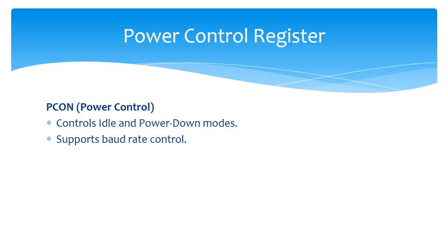You have the next control register, which is called the power control register. PCON will have some bits for serial communication too, that is for the baud rate control, and again this can control the power modes during idle state.